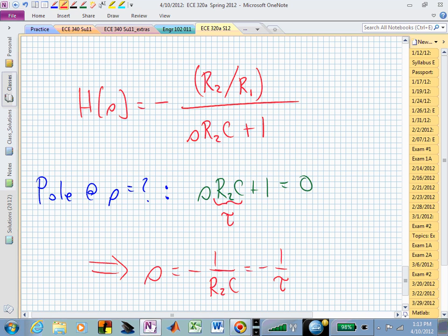But if you don't, then you'll have a break, and then you'll have another break. And you'll just say, well, my low-pass filter bandwidth is where I get my first break. And then your next break is wherever your other pole is. So now, in terms of our Bode plot, you're going to have these 2 transitions depending on where your poles are located. And hopefully that will make sense if we get that far, but I'm going pretty slow because I'm so excited about what we're talking about.